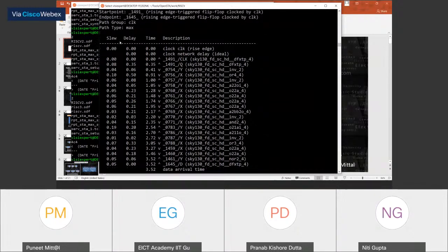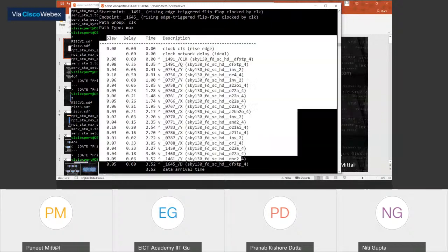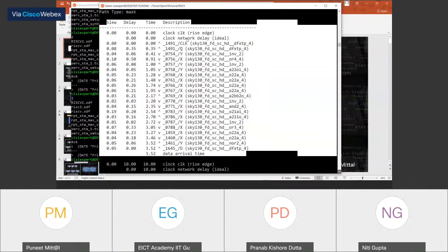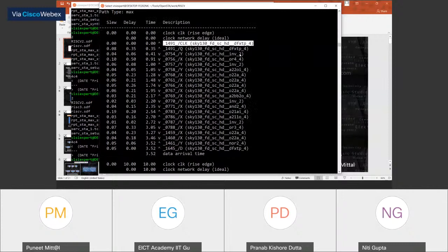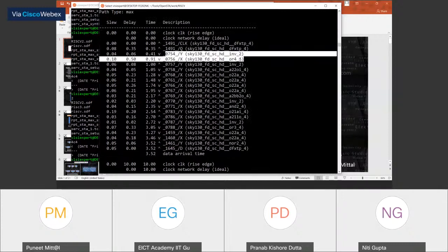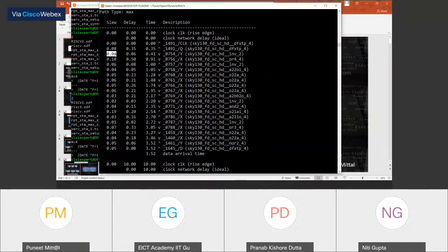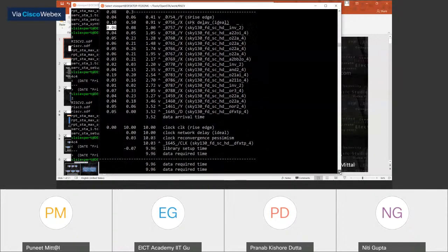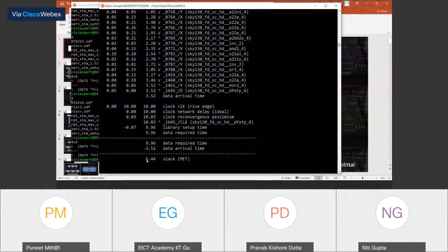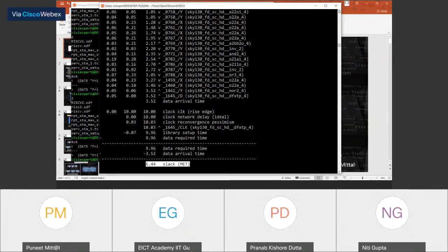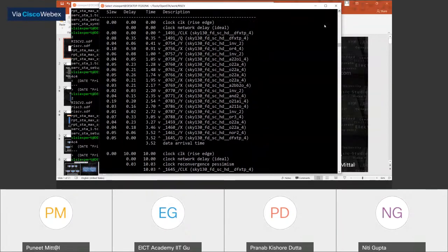Right now, the thing which I want to show you is what we were talking about yesterday regarding the slew. If you want to do it, you can check it in this particular way. For every input and output combination, you can see they are also providing you the slew, the transition. Now, in our case, luckily, all these flags are meeting, so there is no problem. But in your case, if you are going to use any particular file, any particular design, and if there are